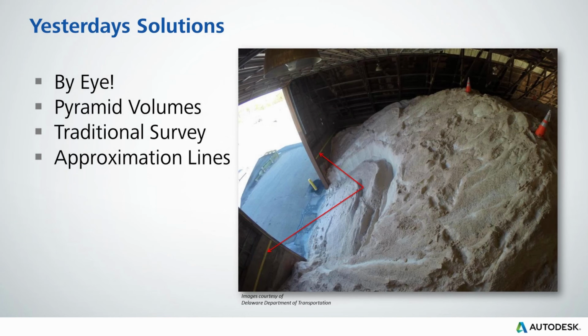So I was recently down in Delaware, as I mentioned earlier, and they're using this method along with some others, the traditional survey method, where they've literally just marked out lines on their salt shed walls. This is, of course, applicable only if you have indoor facilities for some of your stockpiles. And if the height of the pile is at a certain line, then you have an approximate volume of X amount, whatever that is.